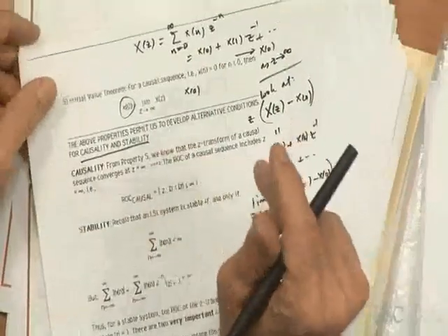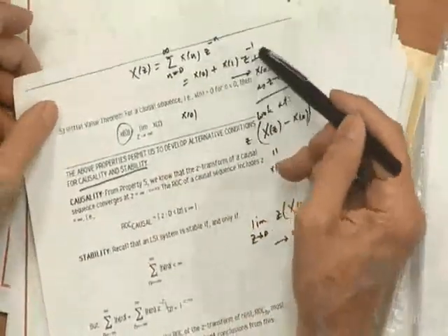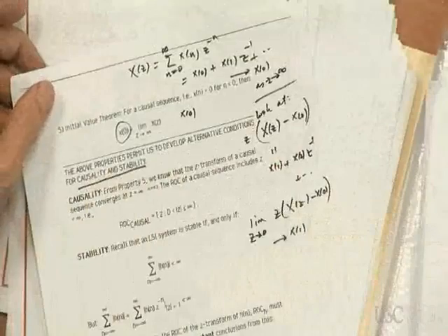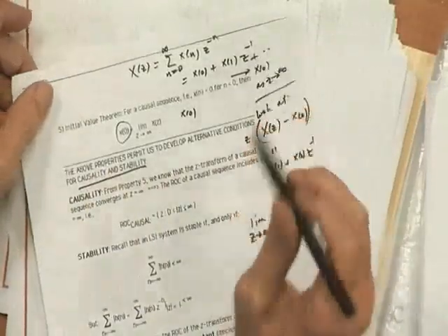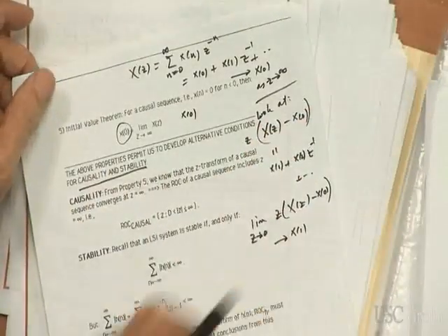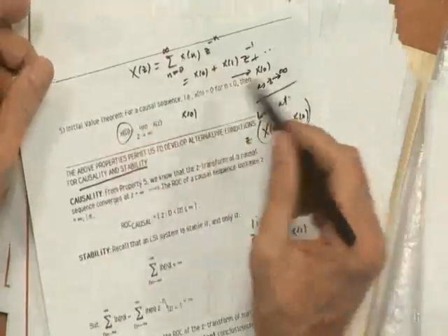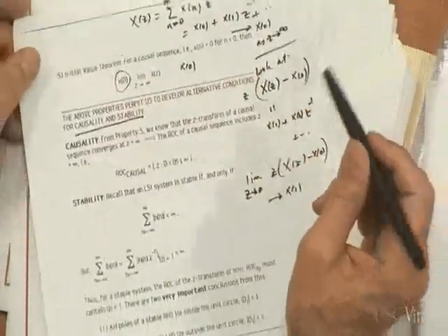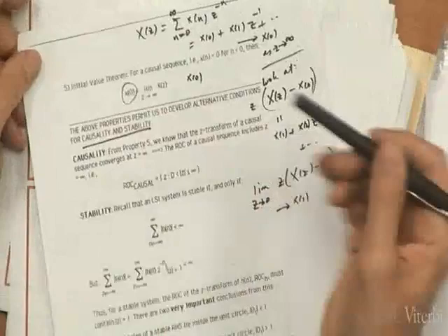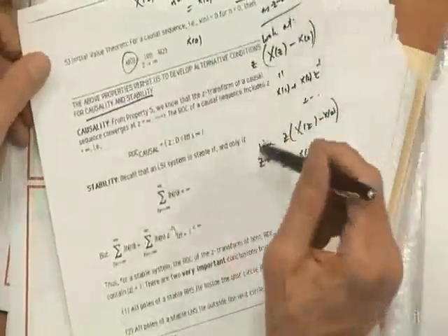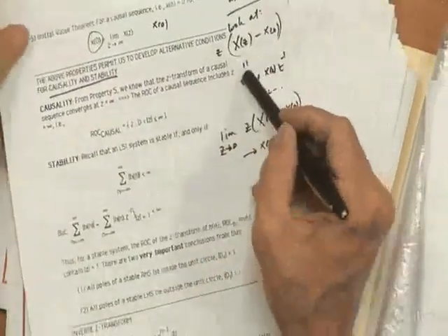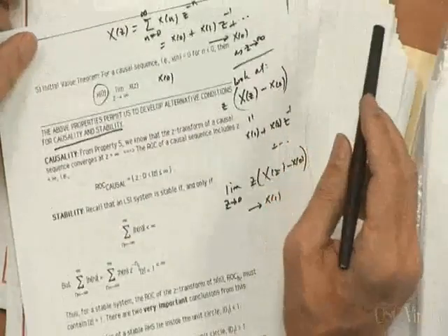Now if it is causal, then you will only have inverse powers of z. So sure enough, you can let z go to infinity. In other words, the region of convergence would include infinity. So that makes perfect sense. And if you want to go a step further, we proved a lemma to this, that the second point in the sequence can be derived from this formula.